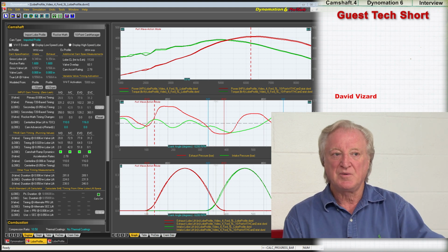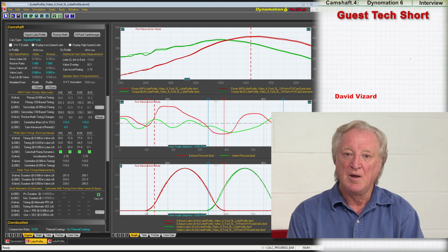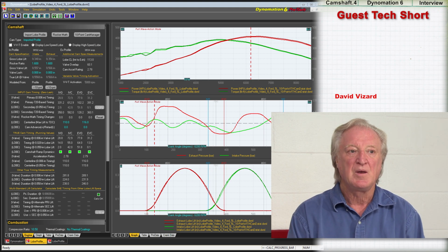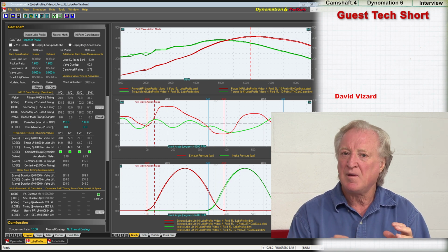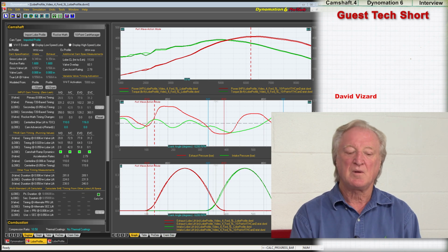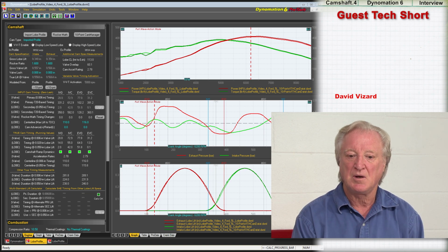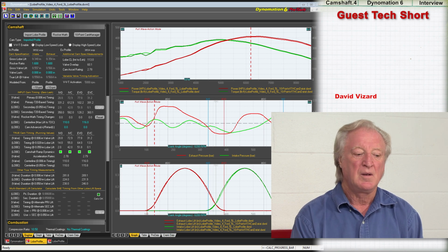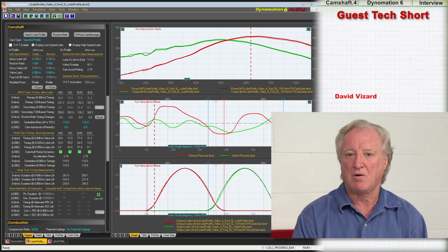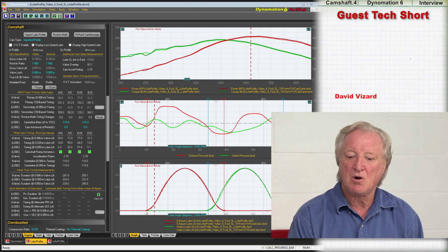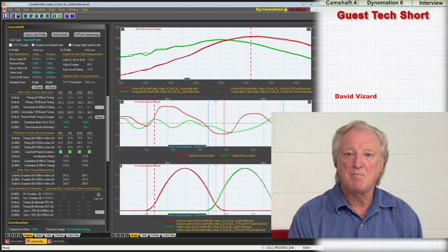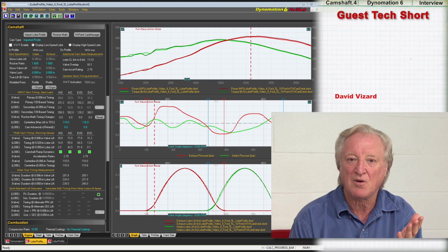With both valves open, the exhaust can scavenge the chamber and start the intake charge coming in. So it's now filled the combustion chamber up, and at that point the piston has not even started to go down the bore. To give you an idea of how important this overlap area can be, on a typical 2-valve race engine, something like a NASCAR Cup car engine, the scavenging effect is so strong that the charge in the intake port is actually moving at over 90 miles an hour into the cylinder, and the piston's parked at top dead center.